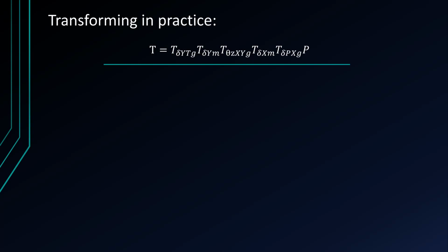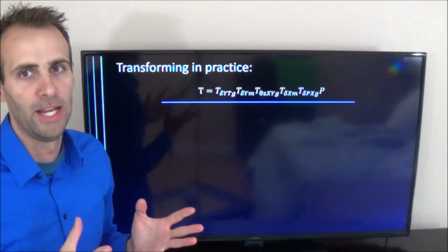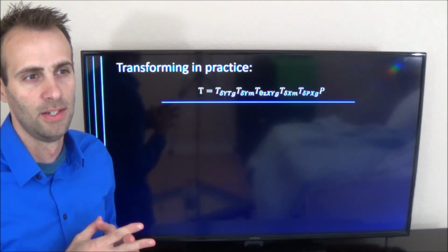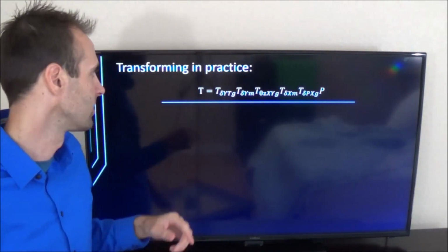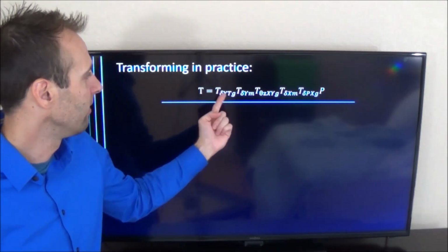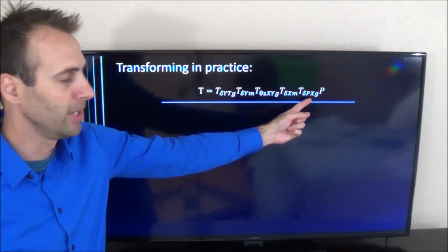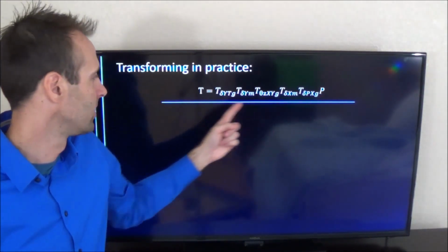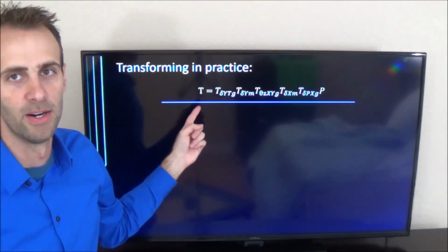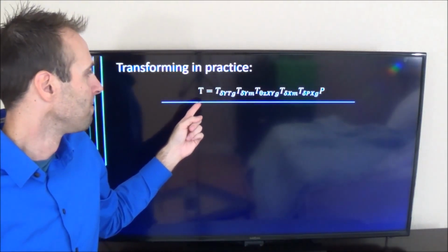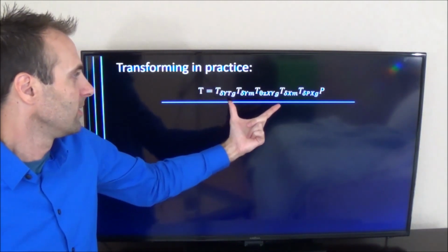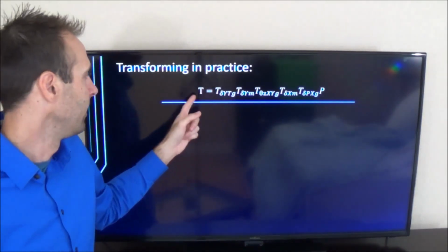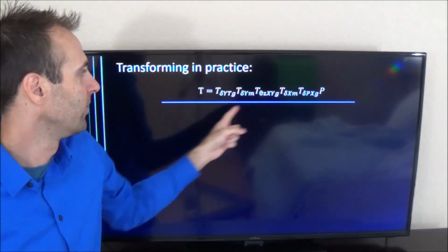Everything that we've talked about up to now mathematically has been forward transformations. That means that if I know everything within all of my transformation matrices, I can go from one coordinate system to another, in this case part to the tool. Well, that doesn't help me with saying if I know these, how do I get there?